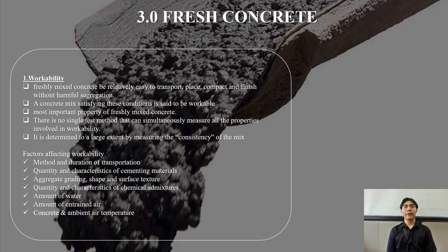There are factors affecting workability. They are the method and duration of transportation, quantity and characteristics of cementing materials, aggregate grading, shape and surface texture, quantity and characteristics of chemical admixture, amount of water, amount of entrained air, and concrete and ambient air temperature.